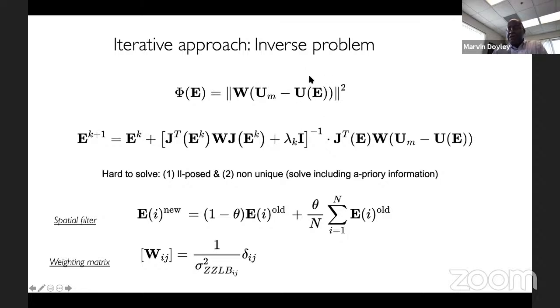And for the model, we just model this using finite elements. And then once we do that, we just minimize this with respect to E, the Young's modulus, and end up with this equation. Again, ignore the W. I'll talk about the W in a minute. And so we have our little Jacobian here. So Jacobian transpose, and we multiply by the Jacobian, and that will give you our SCN.